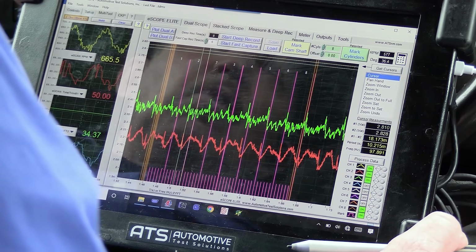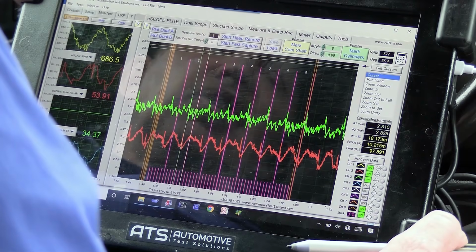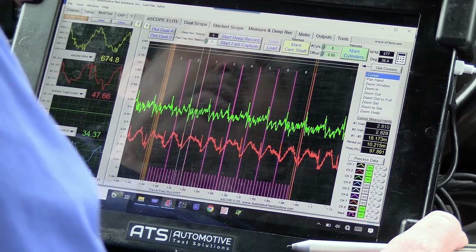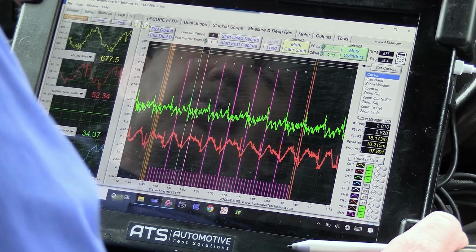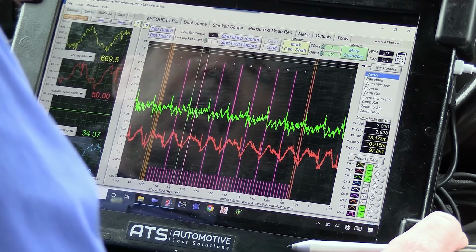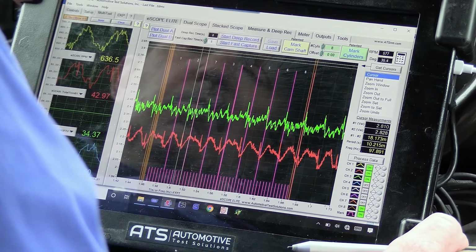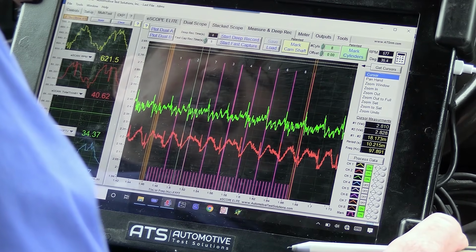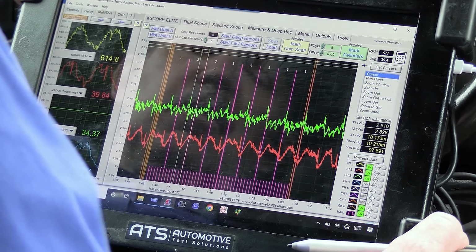But no, when you get into it, you're stretching the chain out, and when you get out of it, the chain gets all loose and it starts whipping. That's what's going on. And now it's just gotten bad because we've been running it so long, the chain's hot and it's stretched out more. That's what's going on here, guys. It's just gotten worse because it's hot. This is incredible. What a crazy car, guys. This is a crazy car.